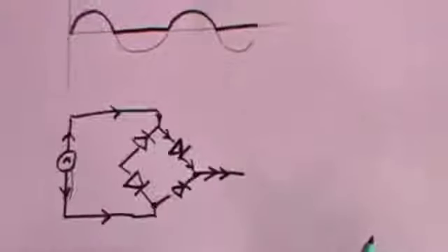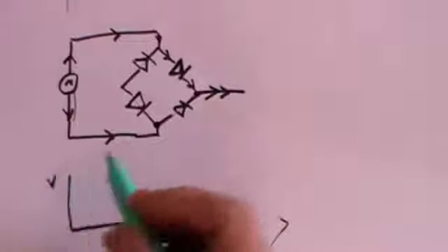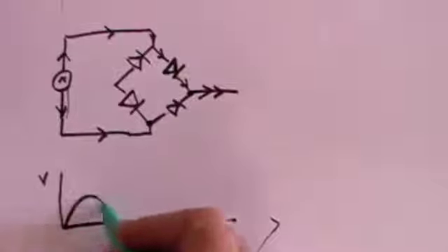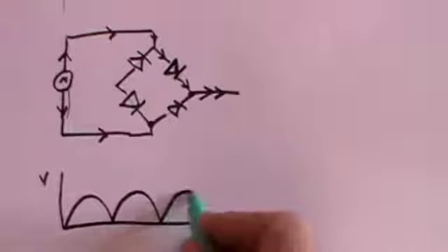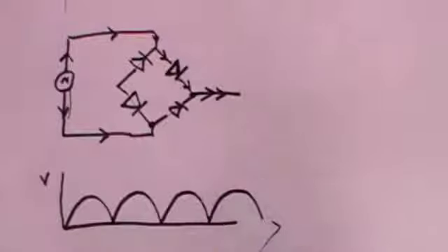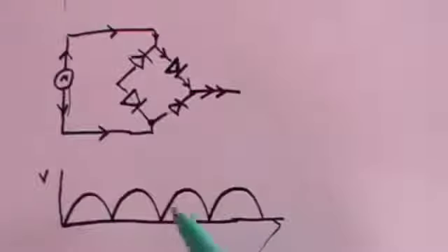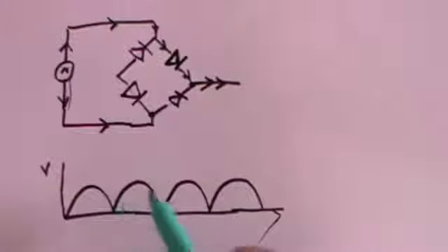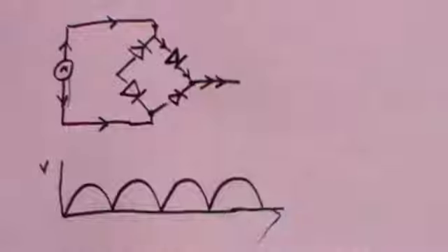And so what you get from that is, if this is the voltage or indeed the current, then you get this. In other words, the current is always in the same direction, but of course it's still varying from 0 to the maximum. And although that's helpful, we still haven't got any negative current, and half the time we have no current at all. It's still not going to be very good for our computers. So it's helpful, but we're not there yet.